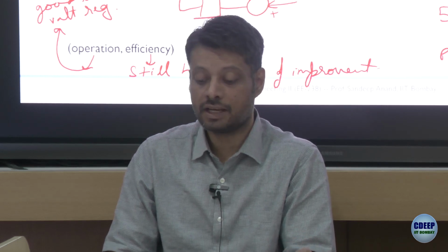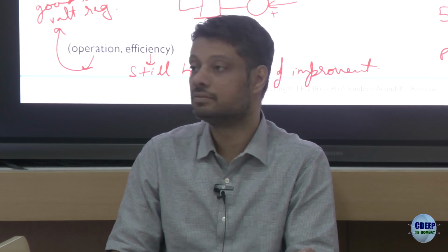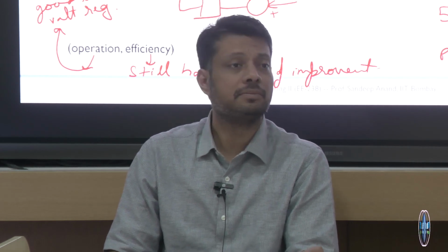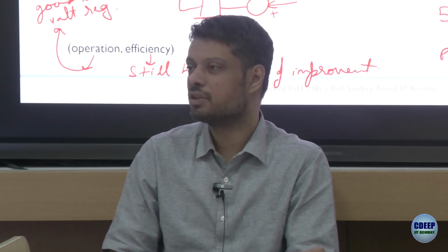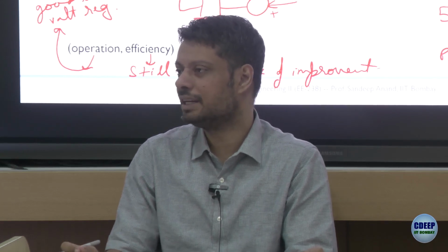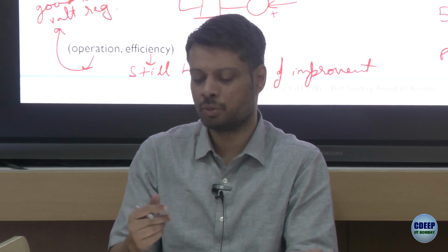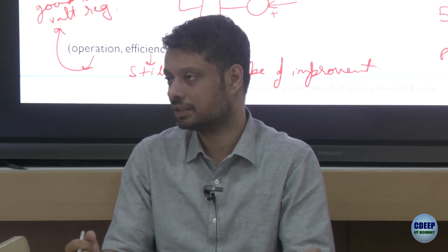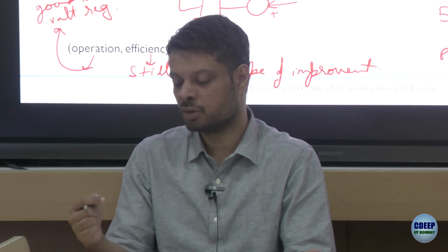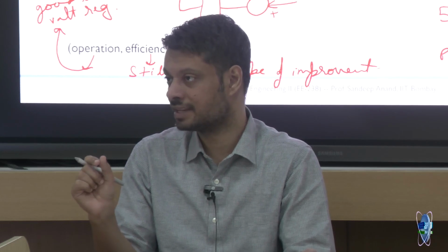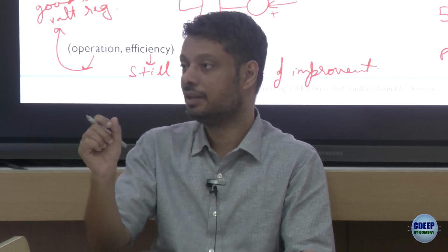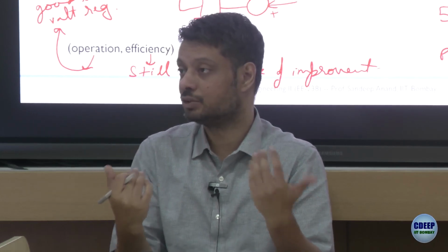Oh, shunt was there. Anyone remembers why there was a shunt? Correct. So if you completely remove the load or the load becomes very negligible, your system may no longer be a controllable system, because at the output you may have some sensitivities. How much gate voltage you can change? If you change it slightly, suddenly the output voltage will jump. There is no way to reduce the output voltage. There is only one way of control.